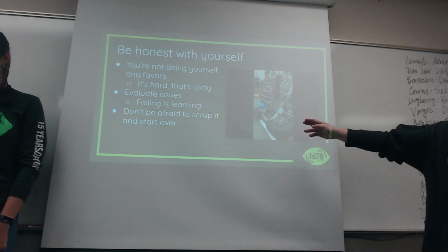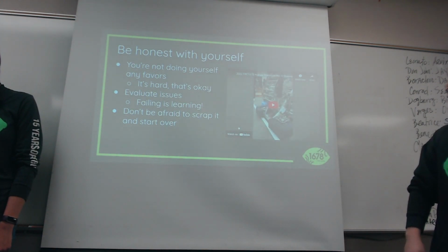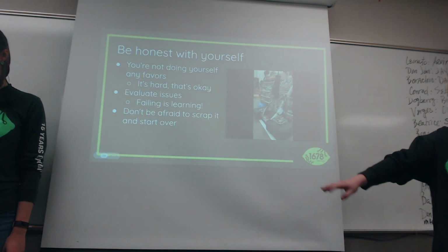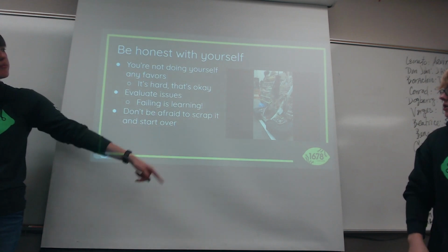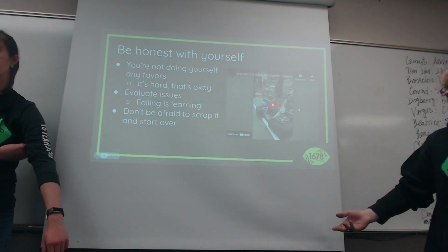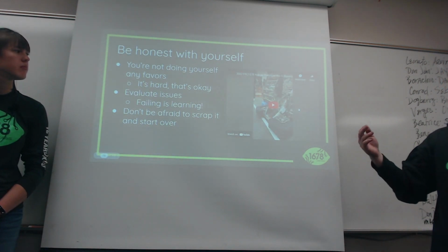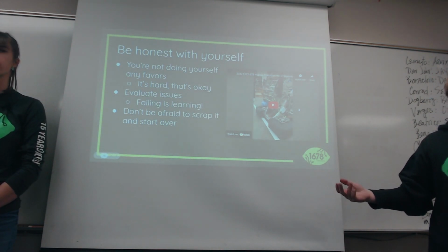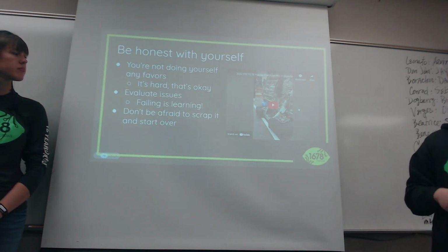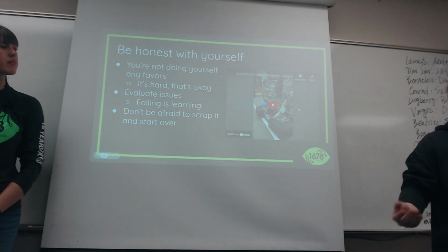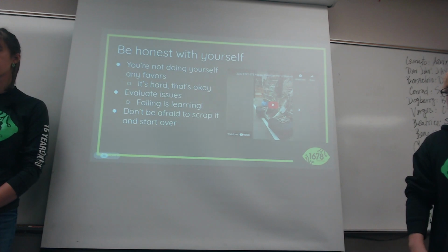And this is an example of things going wrong. This ball was supposed to be ejected, but as you can see, the ramp was unfortunately just not moving fast enough. This was a pneumatically activated ramp, and we could not get it functioning at the time. Here the ramp tries to come up to let the ball through, and we just don't have the time to let that happen. So we had to say, okay, this isn't really feasible for us to make work given the hardware that we're using. If we fundamentally can't make it work, you have to scrap and start over again. If there's a problem that's pretty fundamental, you have to either realize how you can fix it or figure out a new idea to deal with it instead of the one you're currently using.